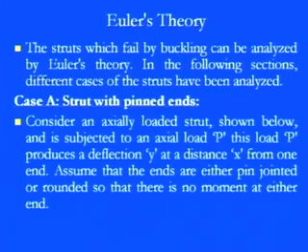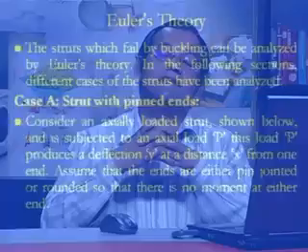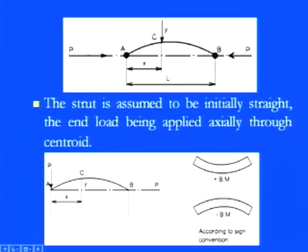That's what we generally use when a simply supported beam has supports from the bottom. But here we are saying that these are pin joints. So this strut is just hanging under pin joint action, and the load is applied in the axial direction.